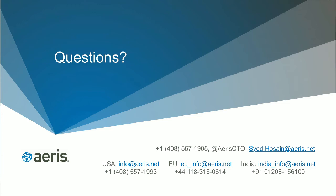First one is pick a technology that you think is going to last longer than the expected life cycle of your product. So for example, if you have an application that can take advantage of the LPWA technologies, that's going to be around potentially longer than the others. If you're developing today, clearly you do not want to do a 2G or 3G application because in some countries like the US or Singapore, 2G doesn't even exist. And in other countries, it does work today and it will work for the next few years, possibly through the middle of the next decade. There is an end game in sight.